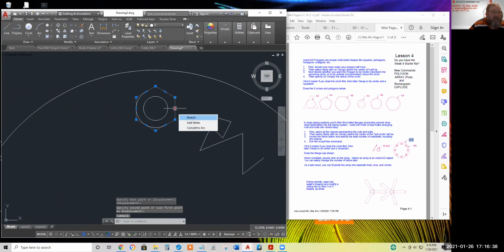A polygon is a special shaped polyline. If you want to delete a side of the polygon, explode the polygon, and it'll go to a lower form of life, namely a regular line.